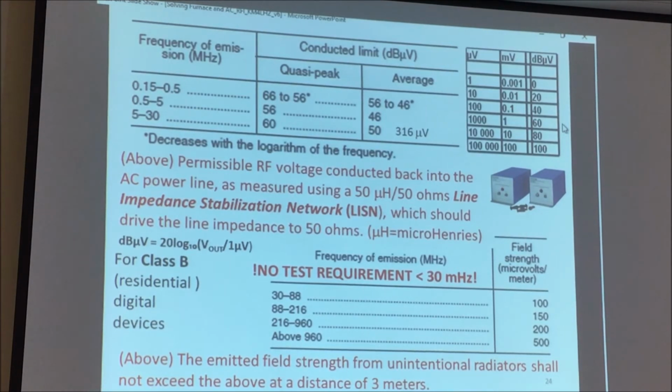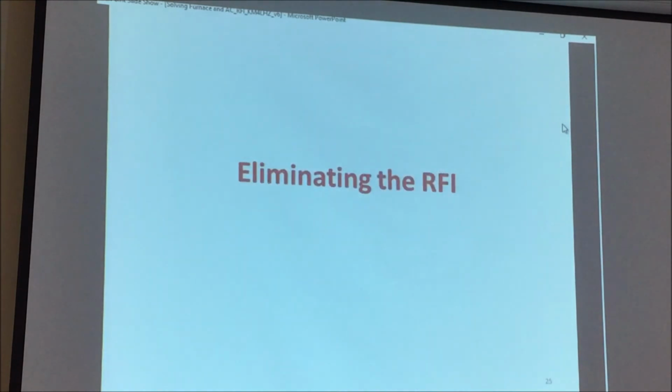Now, I talked again to my expert friend, and he said that Regal Beloit is actually starting to test for emission, but it's tricky because emission is very contingent upon the particular wiring you use, how things are grounded, what the wiring harness is, and so forth. But there is actually no requirement for manufacturers to test to see if an ECM radiates any field below 30 megahertz.